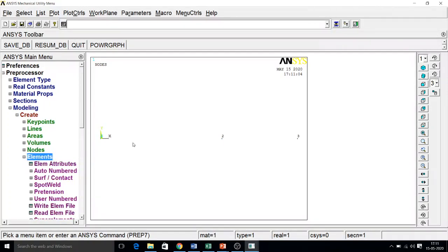In the previous sessions you have directly created the element between node number 1 and 2 and between 2 and 3, but in this problem please take care that I have a first portion which is of steel and second is of copper, where the metal properties are different. Therefore we need to call out that particular metal property while creating that particular element. So when I come to the first portion, it is the steel portion. The Young's modulus for the steel portion is 2 into 10 to the power of 5, and the area is also a different value. Therefore, please remember where you have created those values, and in those particular attributes you have to call them out.